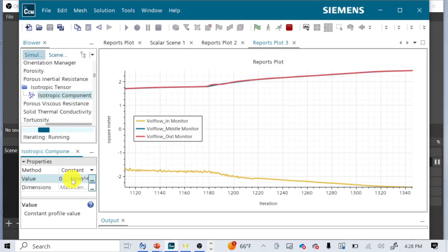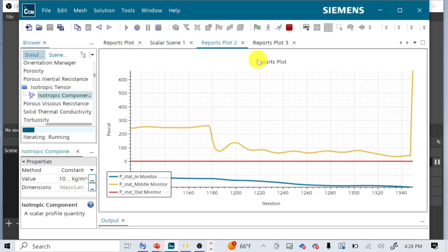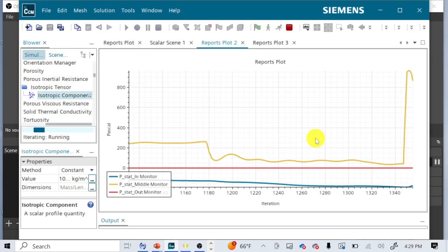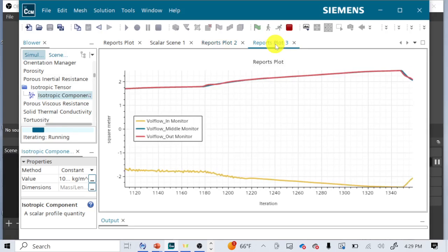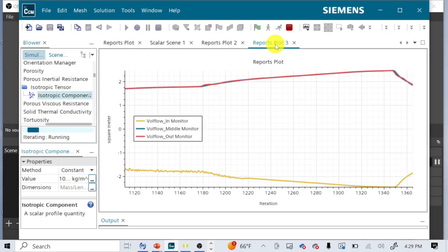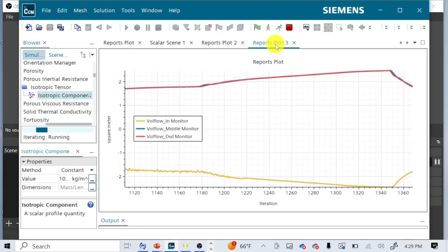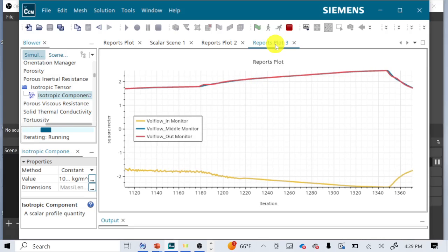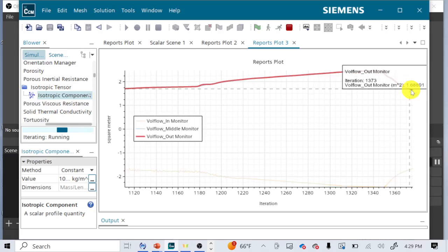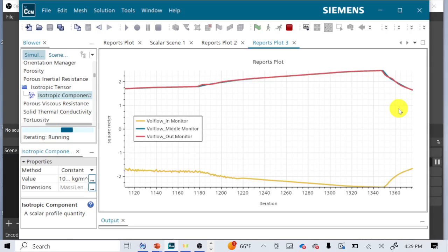I'm just going to change this to a much higher value of I, and we'll see what effect that has. This is 10, I think. Theoretically, you crank that up significantly higher. Maybe it's 100, maybe it's 1,000, but if you make that higher and higher, it's going to generate more and more resistance. It will never quite be a wall. It will never completely seal it off, but it will get really close. So I don't know where this is going to converge, but clearly we have just reduced the amount of flow considerably. It's already moving less than it was before, and that is still trending very noticeably down.